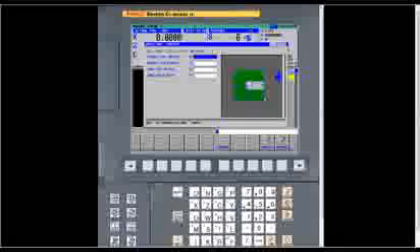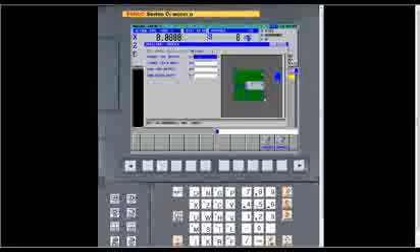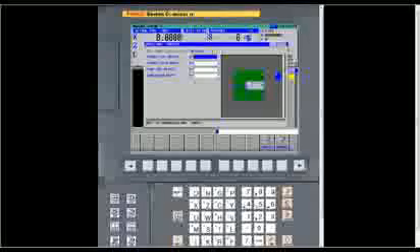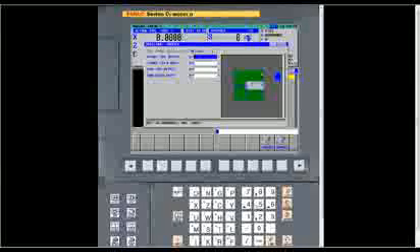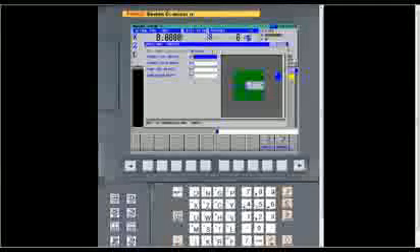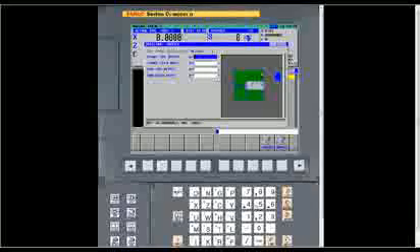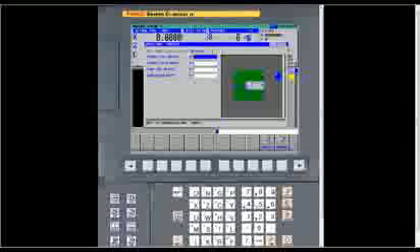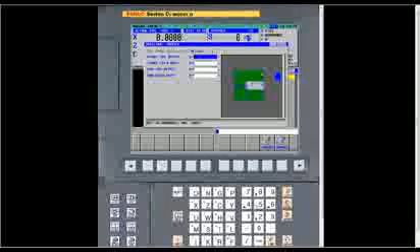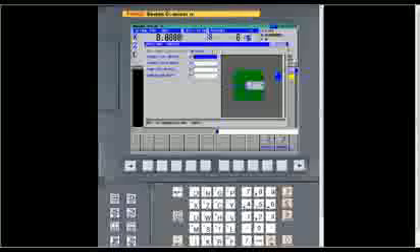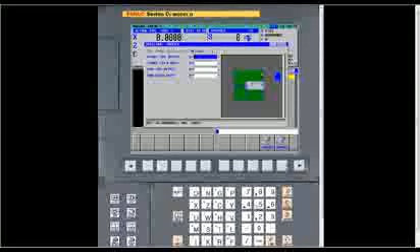So that's very simple. Then it also has detail data. And again, all four of these have asterisks next to them, so you do not always have to answer that information. But what this detail is, say you had a very large drill and you wanted to start it out at a much slower feed rate than what you would actually want it once it got fully engaged. That's what this is for, to where you can start out at a slower feed rate and then increasingly make it faster. So that's what a drill cycle looks like.